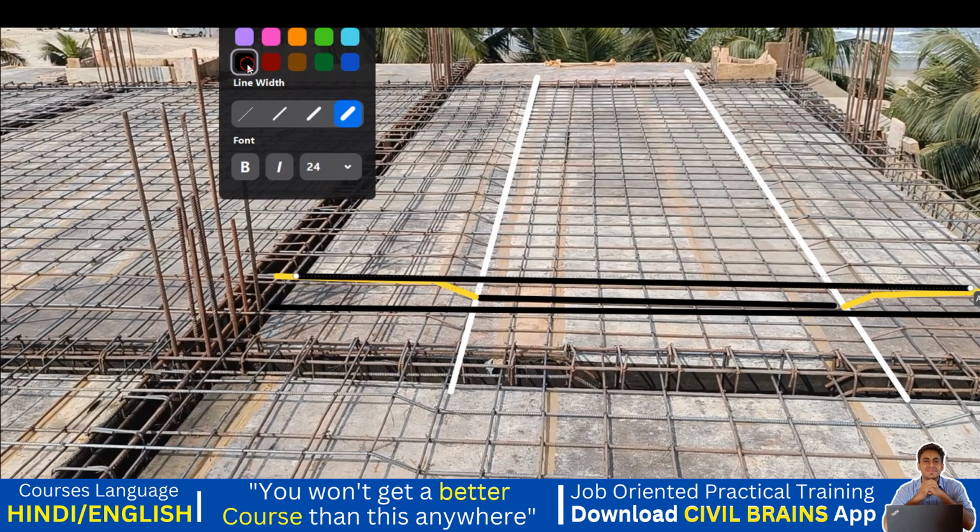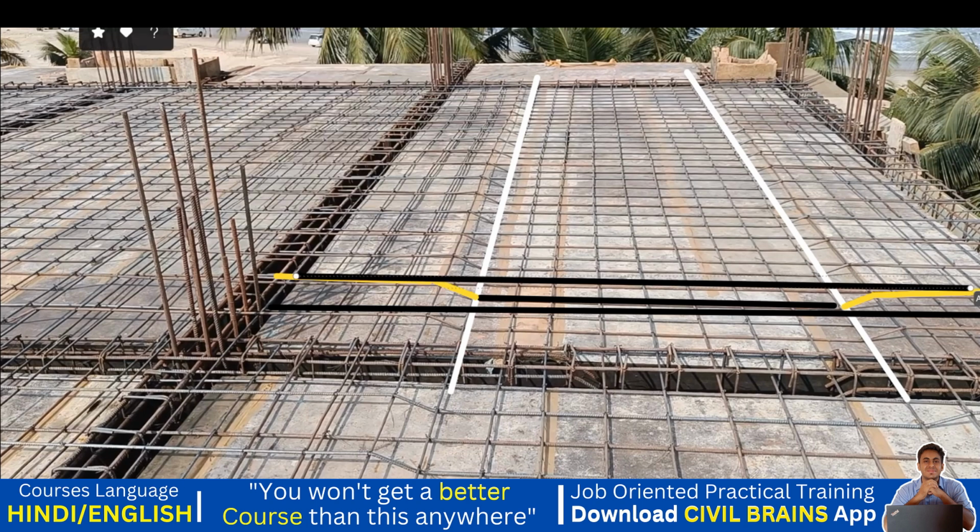After that, the next bar I will give straight up to this length, because here my sagging bending moment is more. And after that I'll crank the bar, because there was a hogging bending moment. Got it? So this is the main idea behind that.